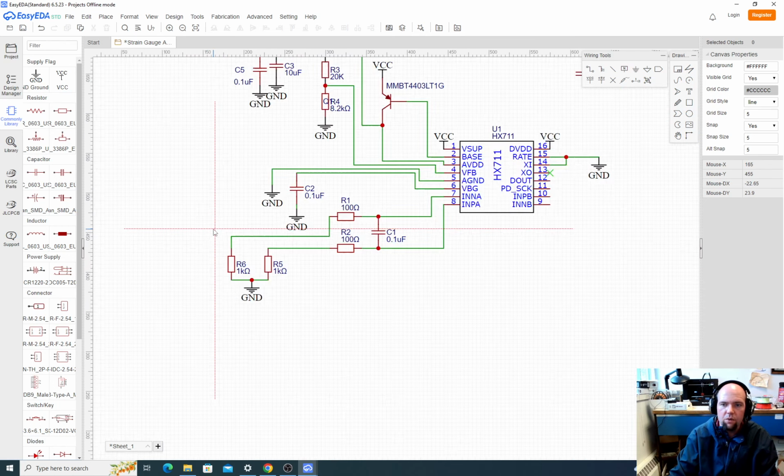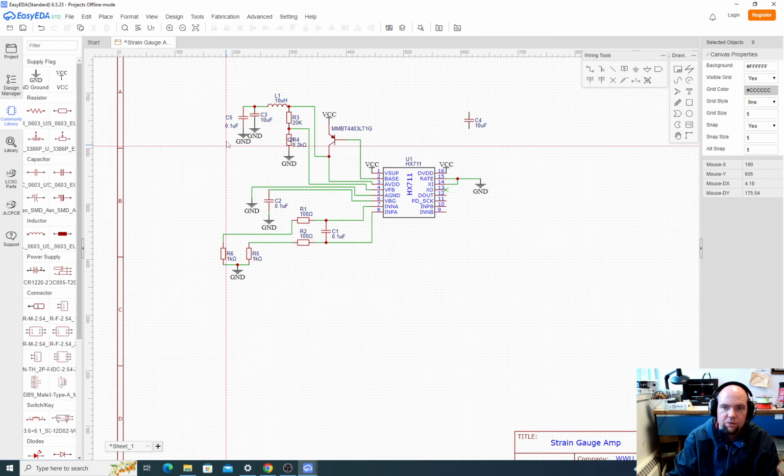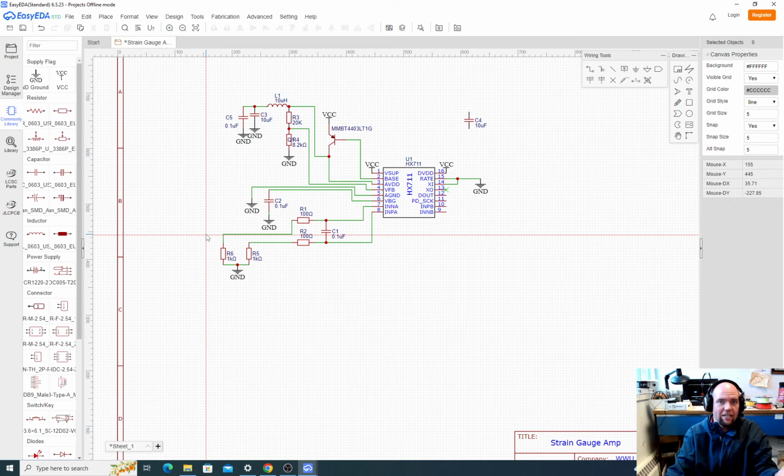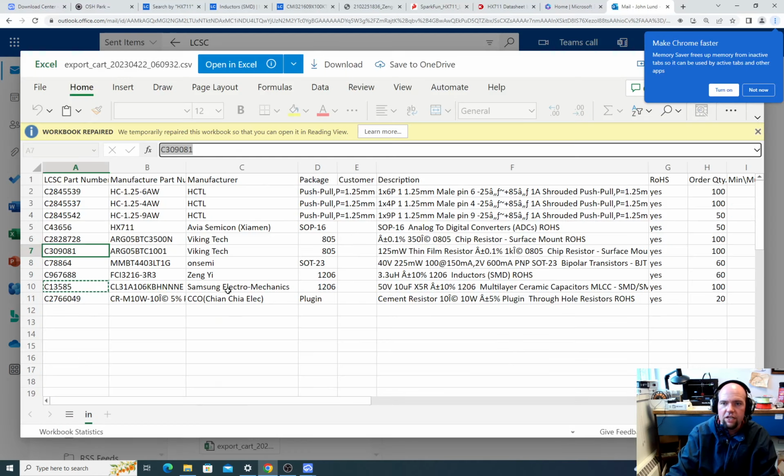So basically now what's going out to our strain gauge is we have power going out to our strain gauge here. And we're gonna have a connection to the top half of the bridge, which has to be here and here. So we have to connect these signals to the top half of the bridge, and we have to get excitation. We don't need the shield or the other wires. So technically we can use a 3-pin connector. If you want to give yourself a connection exactly like what SparkFun did, that's fine too. But let's go back here.